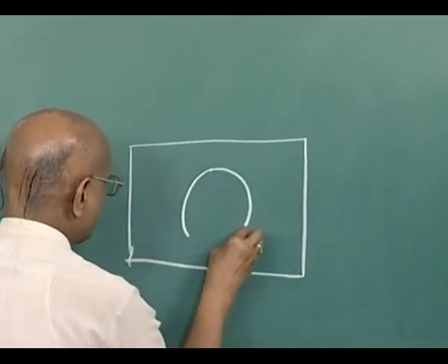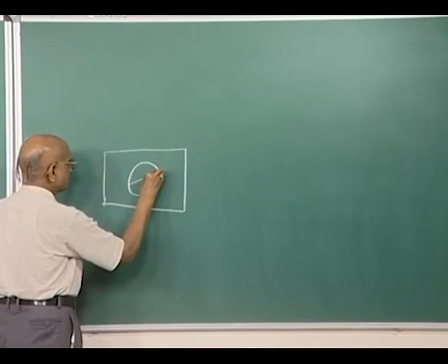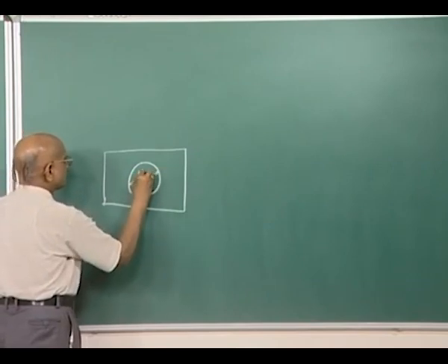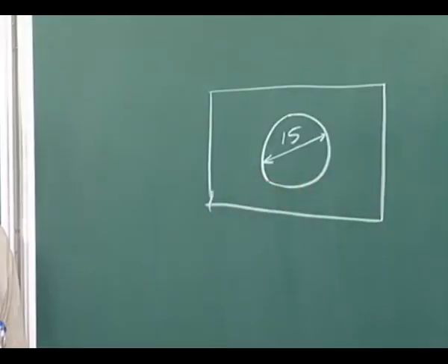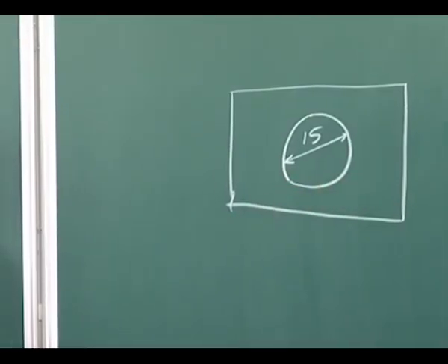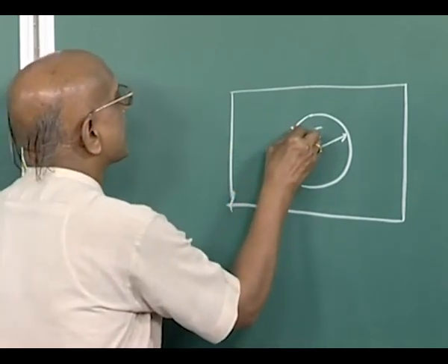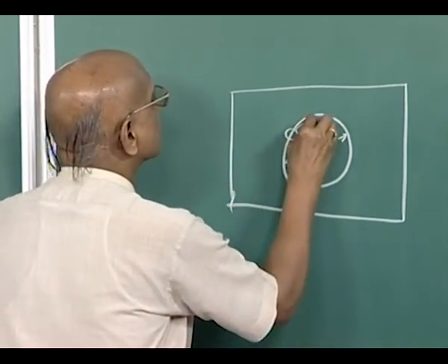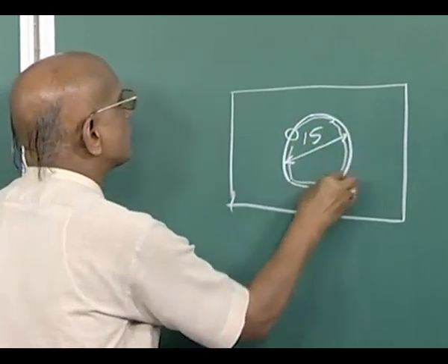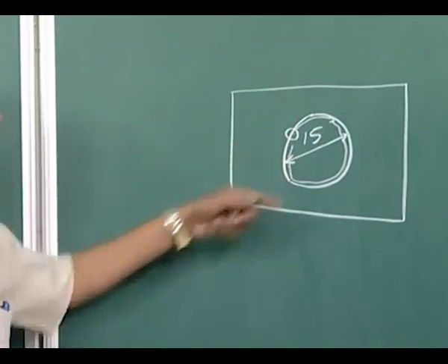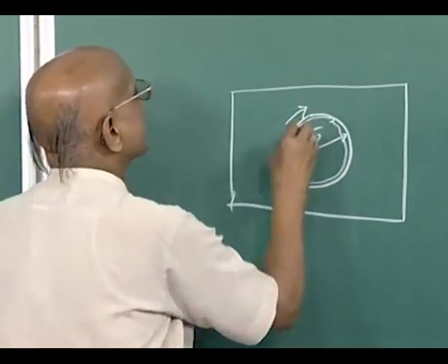then there is no sense in melting and vaporizing the whole of the material of this particular 15 millimeter diameter and depth equal to the depth of the hole to be drilled. So, what is the best way in such cases is you do the trepanning operation. That means you cut the material along the periphery of the hole being drilled. So, once you have moved it through the whole length along this particular periphery by trepanning operation,